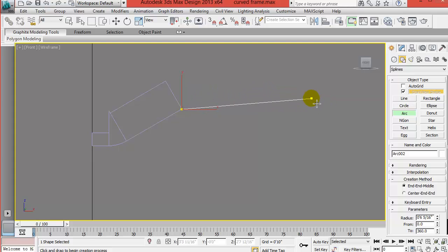And once you click again, you'll see that the arc shows the direction and the angle and the curve pretty much where you want it. And we're going to correct this angle to match this one again. So go into the from parameter of this, and let's make it 90 so we know where we're starting from, and we're going to